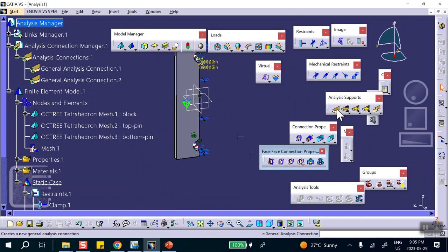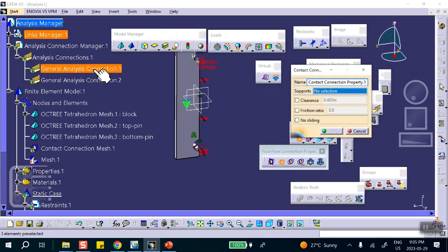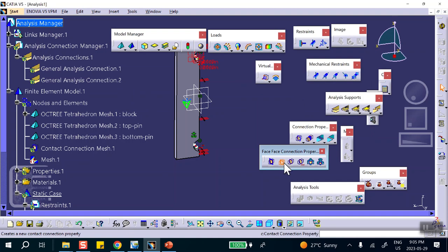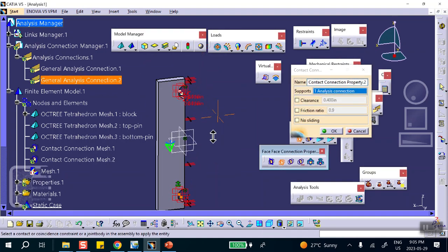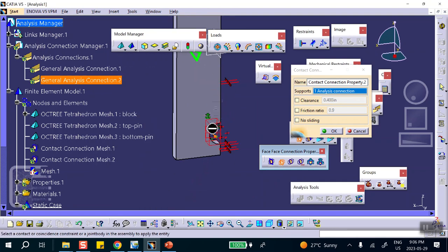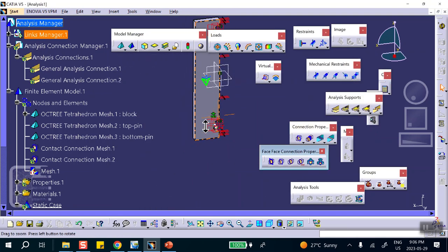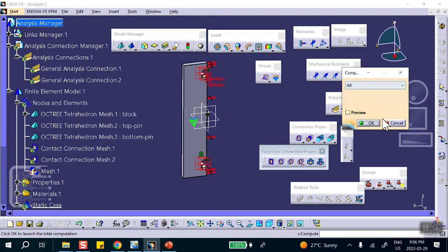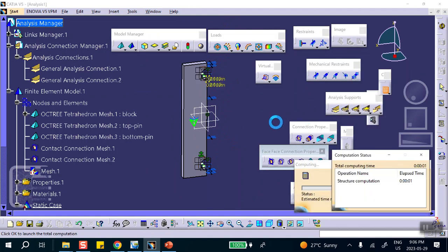This is how you create it. You say these guys are related to each other. Maybe they're siblings, maybe they're friends, maybe they're classmates, okay? So this doesn't say how they're related. These say how they're related. Okay, so this is contact connection. For the first one, you have to do that separately. And then another one for the second one, you cannot simultaneously pick them. See that? Contact. And now run it. I bet this time it will work.